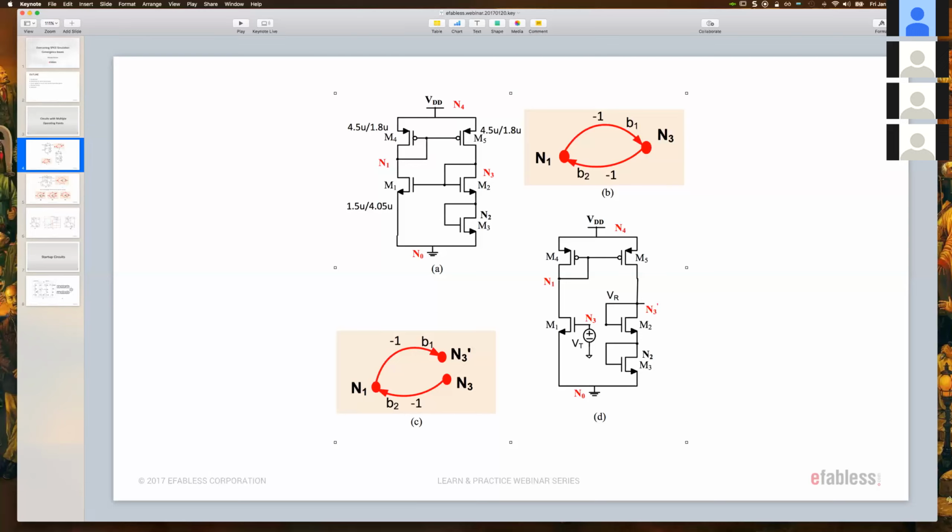The approach to understand the operating point, and the one that works the most, is to understand where the circuit can go if you do some sort of artificial sweep. In this case, that means breaking the feedback loop here, applying the signal directly to that artificial input and seeing what the return is. And obviously, a valid point is where you have a solution where they intersect.